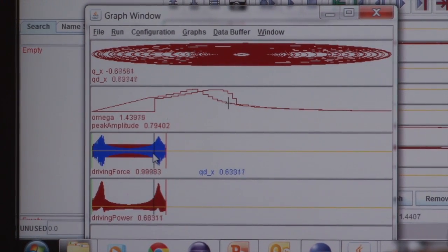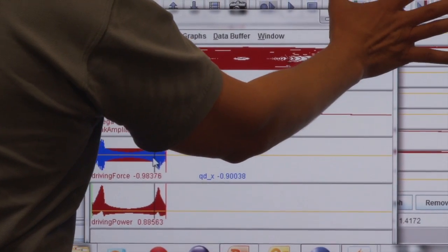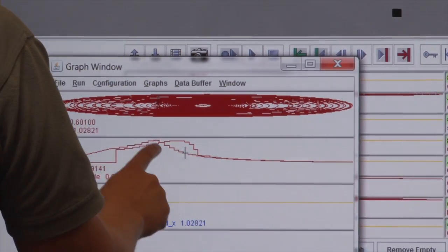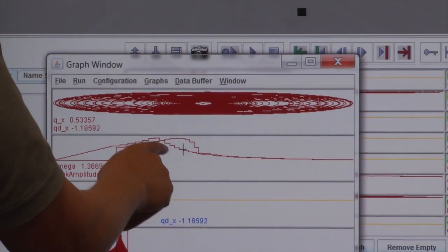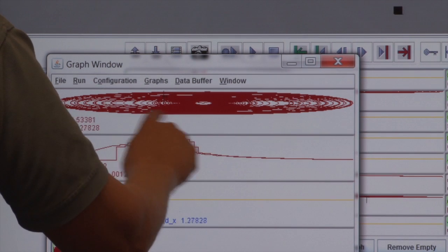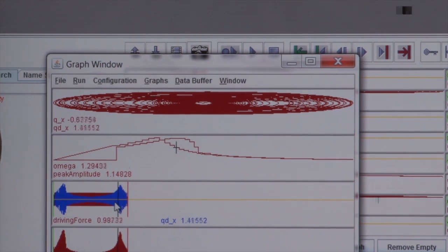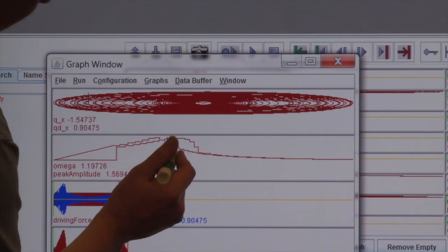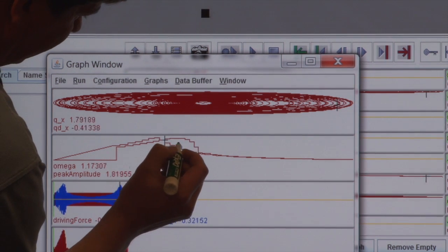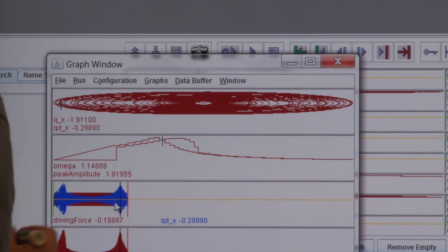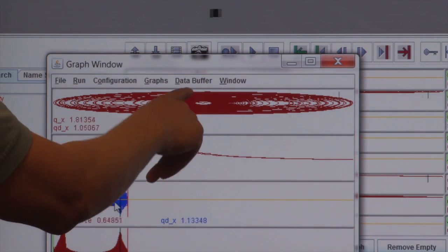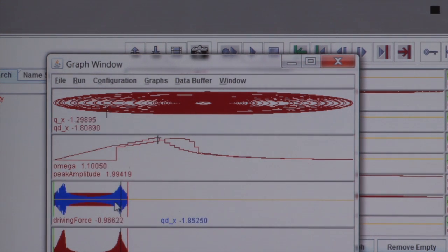And if you watch the amplitude of this, it's still pretty small until you get back to where you can be resonant again, and then it'll spiral back up. So you get this hysteresis curve. In the dead zone, there's a region to the right of the breaking wave where you can't be in that intermediate. There are unstable solutions that would be right here that you could drive it at, but they're unstable. They jump either up or down. Does that make sense?